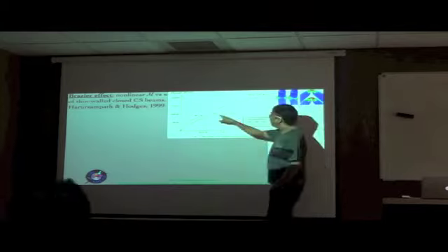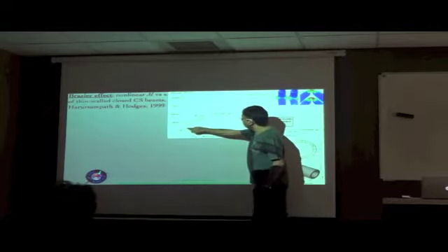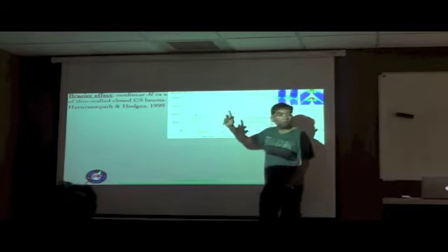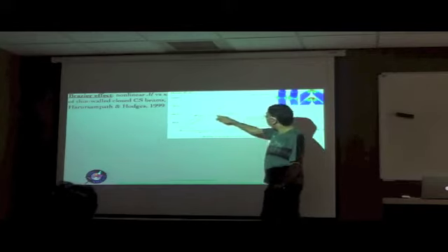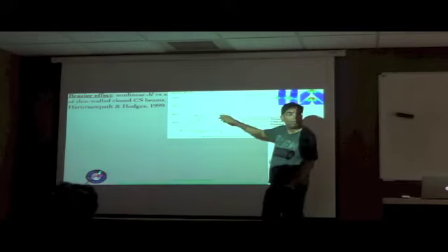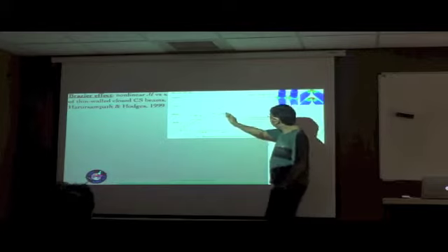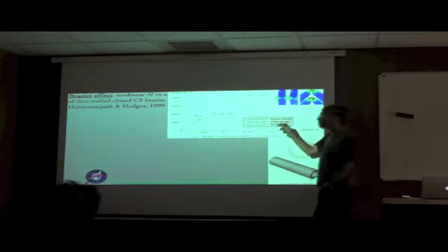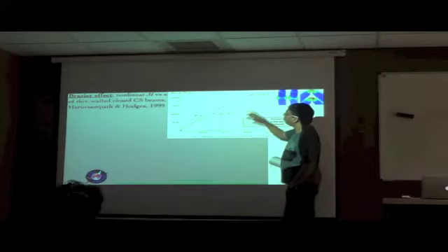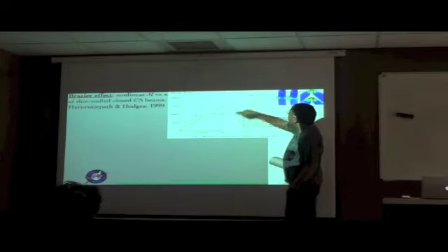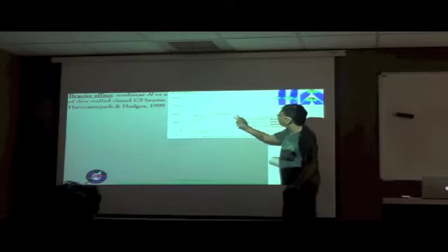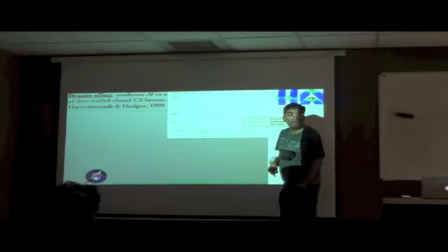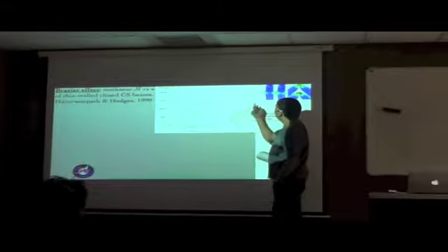Similarly, if you change the layup, again it changes quantitatively but not qualitatively. Once again, you see that it reaches a particular maximum moment that it can take, beyond which the curvature dramatically increases irrespective of the layup that you're looking at. Again, there's another layup over here, slightly different from this. So, in other words, the ordering of the plies will also matter.